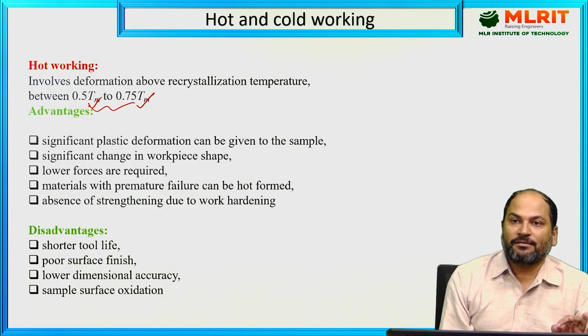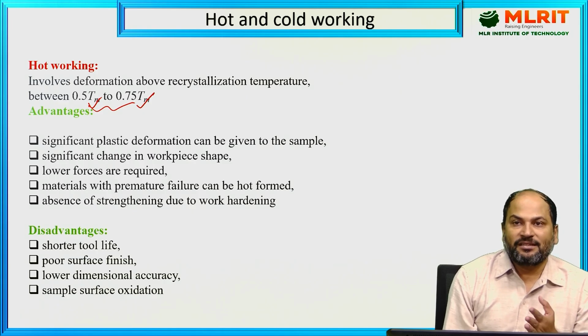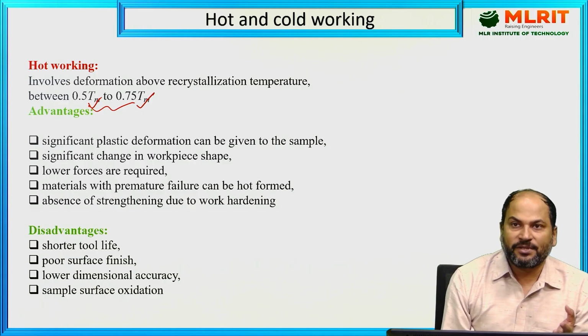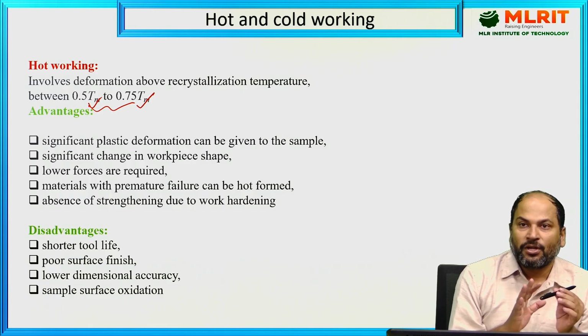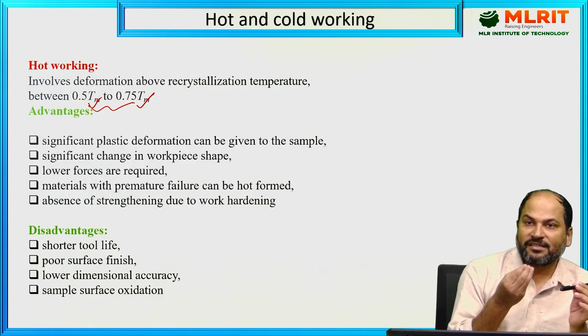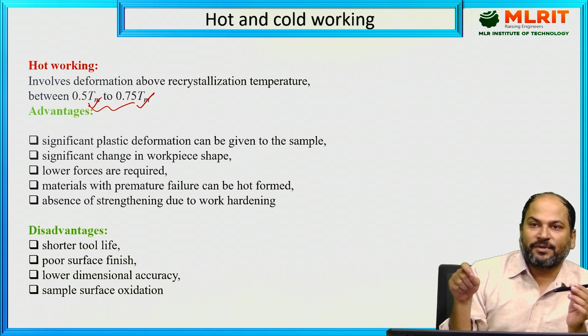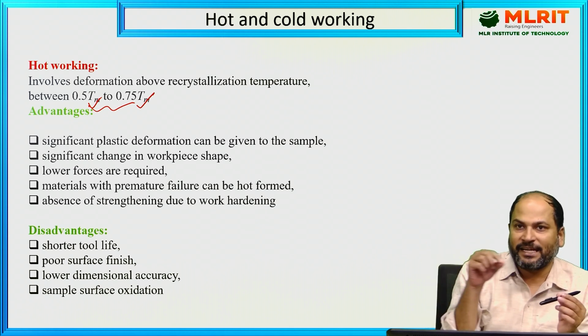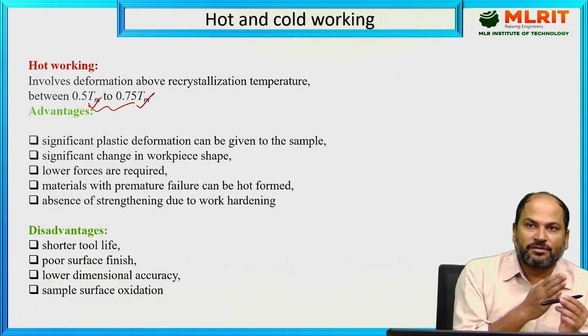What is the reason? Because this depends on many things, whatever material we are talking about and what its history is. History means how it has been cold worked. So the recrystallization temperature is not a sharply defined temperature point. It generally lies in a range depending upon the history of processing of the material, because it depends on many factors.